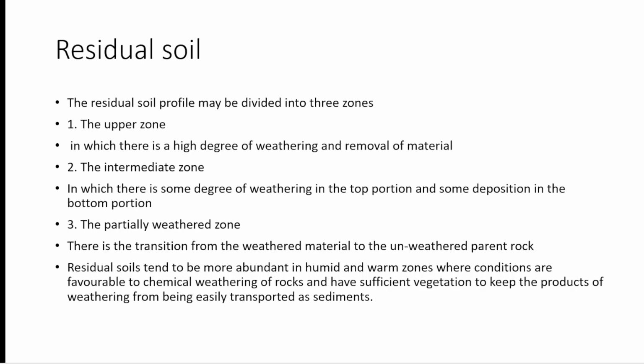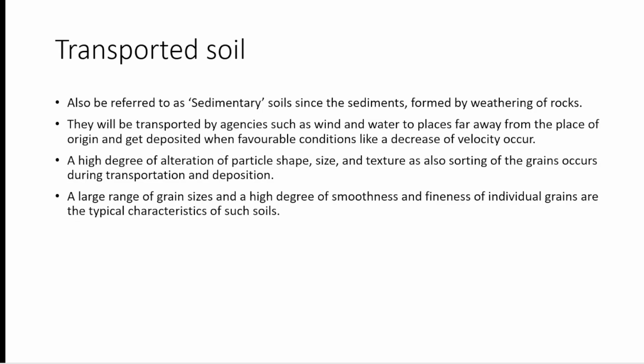Transported soils may also be referred to as sedimentary soils since the sediments, formed by weathering of rocks, will be transported by agencies such as wind and water to places far away from the place of origin and get deposited when favorable conditions like a decrease of velocity occur. A high degree of alteration of particle shape, size, and texture as also sorting of the grains occurs during transportation and deposition. A large range of grain sizes and a high degree of smoothness and fineness of individual grains are the typical characteristics of such soils.